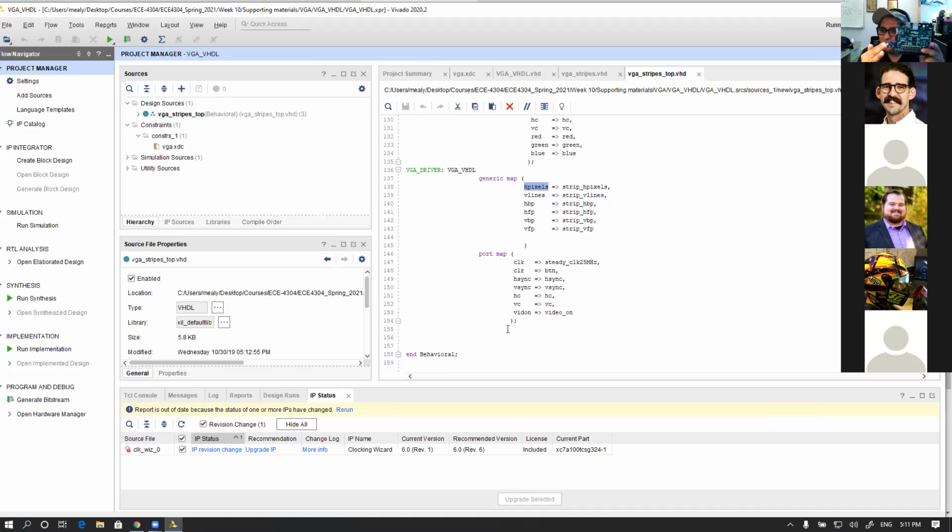I can actually push data from there using UART, while the other one uses the other UART with a different speed. There is one of the projects I used to do for fun, just to play, which is basically have UART here, UART here, UART here, and make this as a router. And every single one is connected to another board, and then the other board connected to other boards. Then you have a big mesh network, and all of them talking to each other at different rates. And each one has a RISC-V processor. All of those guys are talking to each other and pushing data, and I was using it for computer vision. That was a really fun project.